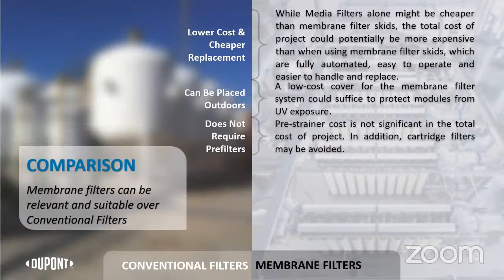There is this belief that sand filters do not require pre-filters. Of course, the membrane treatments do require some pre-treatment, but basket strainers are really not big investments. Rather than killing the membranes by allowing them to face really troublesome water, keeping a small strainer upstream can really make the unit equipped and handle the worst case scenario better.